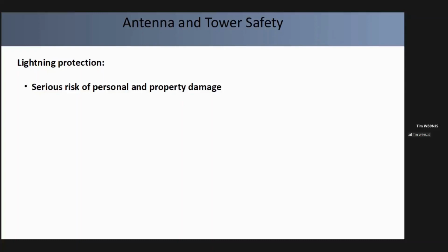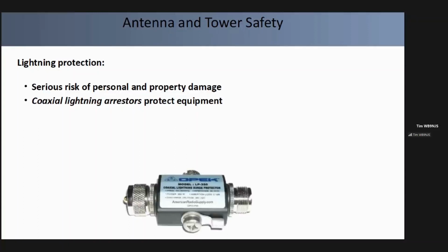Lots of ways to mitigate that. But the one that the test refers to, one of them is coaxial lightning arresters, which protect the equipment and look something like this. Actually, if you could see it, it says right here, coaxial lightning surge protector. You'll notice there's a big ground lug on it and places for the coax to hook up.